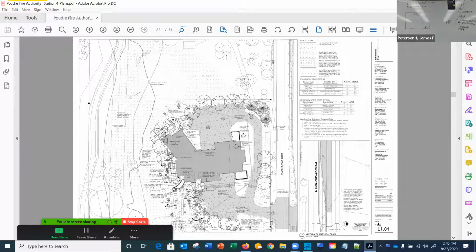We did civil drawings, architectural, structural, mechanical, because that's how you build it. But then the landscape ones here are following civil. Well, again, it's because it's related to the site work, but you might put the trees in last. You might put them in the middle of the project. It sort of depends on when you build maybe the parking lot or the curb islands or wherever those things are going to be. Because you can't plant the trees and then drive dozers and cranes around on this thing. So it's a little out of building sequence. So that's how this semester is going to work: we got a general rule and then there's exceptions.